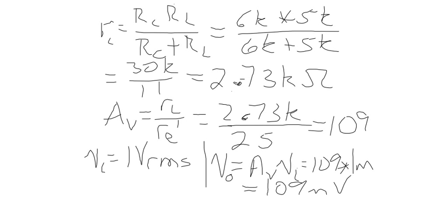And so we can make bigger and bigger gains. We just have to watch our voltage limits, whatever voltage supply we're using. We can't ever put out more than that, and really about half that, because again, our operating point needs to be about halfway in the middle of the load line, so we've got room for the voltage to swing back and forth in either direction.